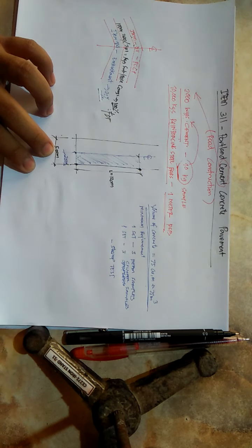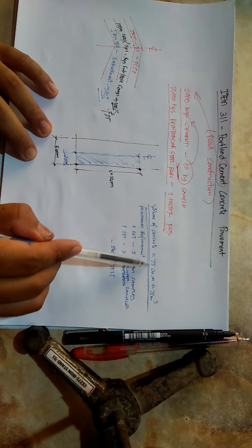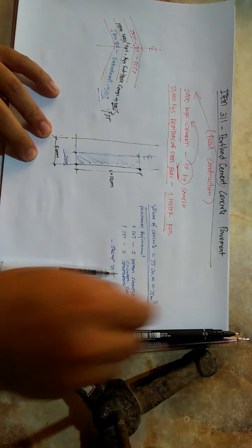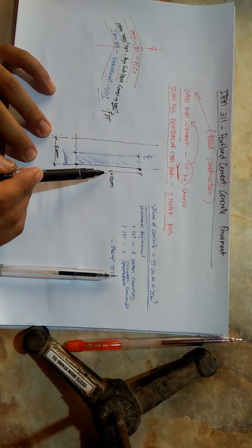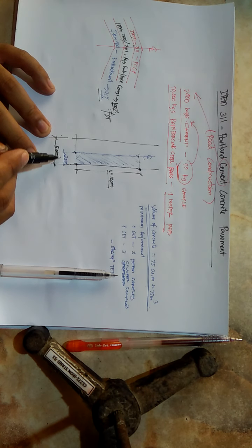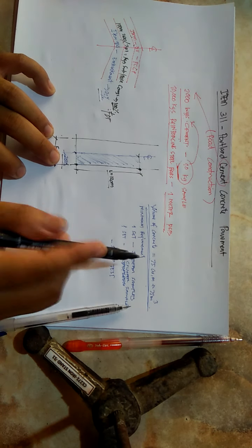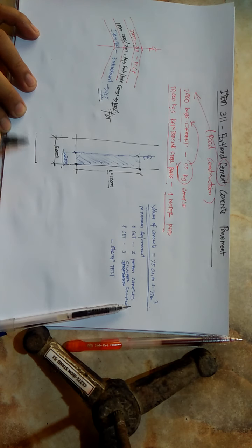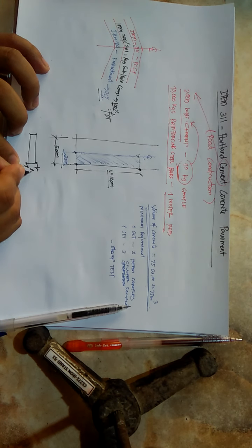Okay? Nakita nyo, binuhusan nila ngayon. And then next, one thing more, you need to calculate first kung naka 75 cubic meter ka na. Example lang, ang binuhusan na ni transit mixer sa maghapon is at a length of 120 meters and at a road width of 2.5 meters. Ngayon, ano bang kulang dyan para maging volume? The thickness. Let's say, ang thickness ngayon nung konkreto natin is 0.25.